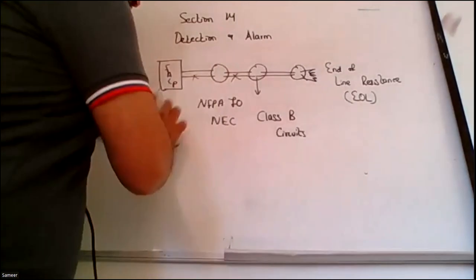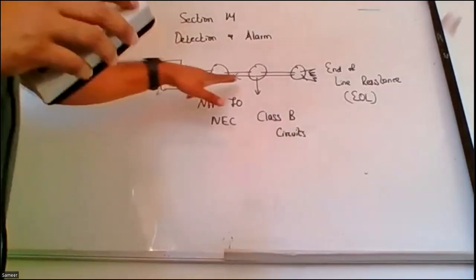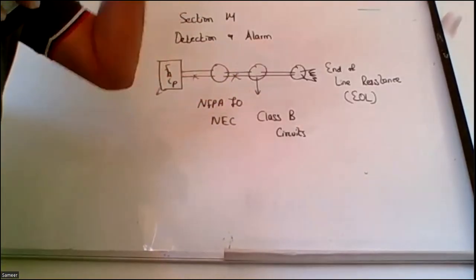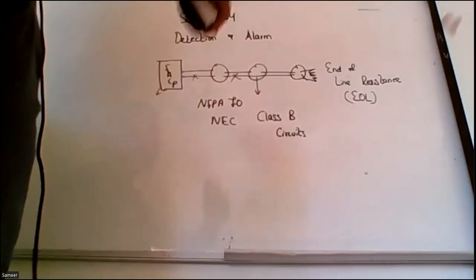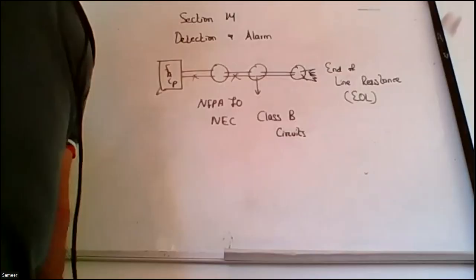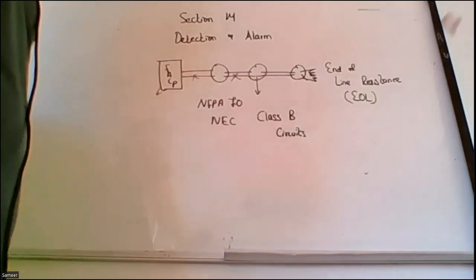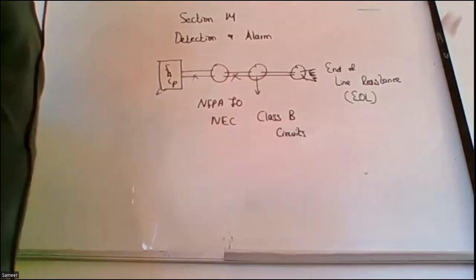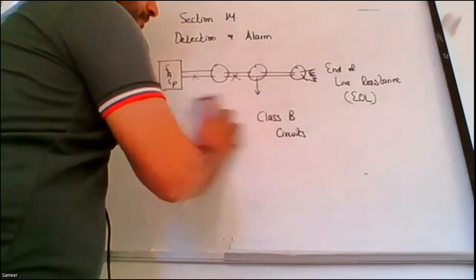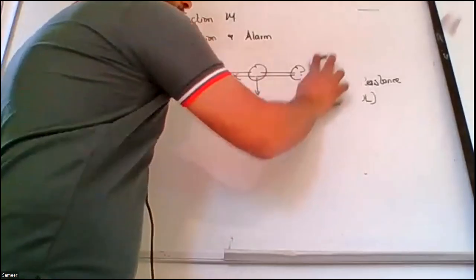Now, what happens in the high-rise building? Two problems are here. First of all, with conductor breakage, the whole circuit disables. And second, the surveillance time is far greater, right? If I have more and more detectors, there is more surveillance time, more time to reach the point of fire. So to deal with these two problems, I go for the next type of system, that is addressable systems.